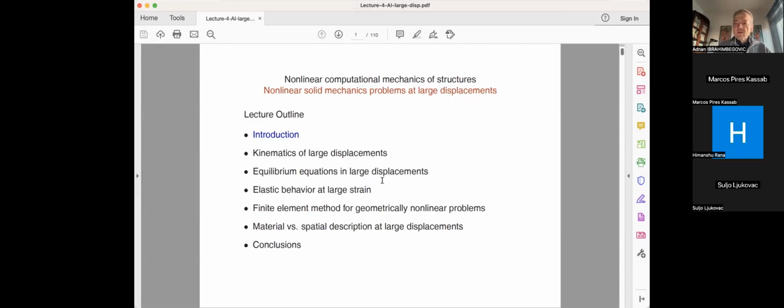And it turns out such a constitutive model cannot really handle everything nicely. In particular, if you have very large compressive strain, that gives a completely unreasonable conclusion that, let's say, squishing some specimen, you need zero stress. Of course, this is a consequence of lack of convexity of the free energy function with respect to these strain measures.